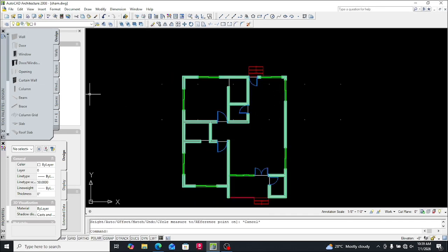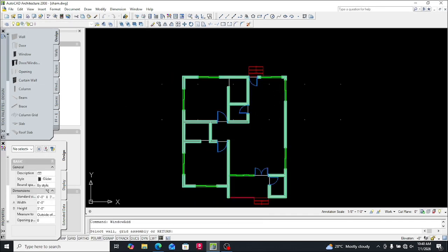After doing that, you have to give a high bay window for the washrooms. The washroom window is called a high bay window or vent window. It is 3 feet by 2 feet. That is, the width is 3 feet and the height is 2 feet.